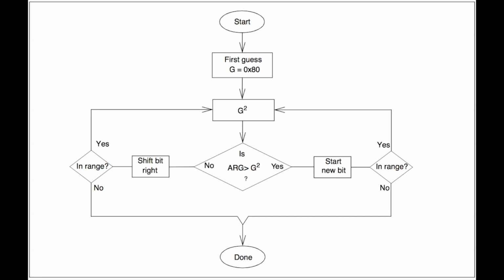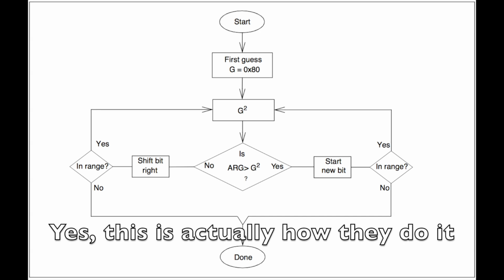So a lot of work goes into writing code for 8-bit processors that cuts a lot of that stuff out. Like square roots are goofy, even division is goofy. Addition, subtraction, it's usually okay with that. Addition's the quickest, multiplication's pretty fast, but you're really dependent on the compiler software to do a lot of the shuffling and twiddling to make that math happen more quickly, and squish that into a format that's easiest for that processor to digest quickly to take the fewest CPU cycles possible. Or just to make it possible at all.